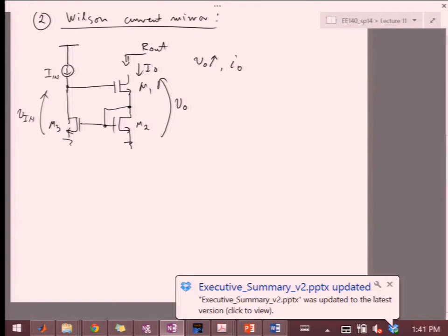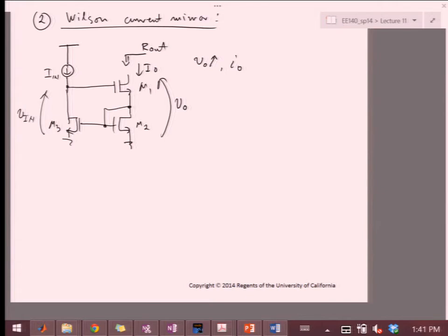It increases because the source has some finite output impedance, right? So if the voltage increases on any given R, your current also increases, right? So knowing that this has some finite output impedance, if I increase the output voltage, likely if there's no other regulation mechanism, this I is also going to increase, right? So if I increases, that means that this VGS also increases because this is diode connected, right? So it maps that increase in I naught to this guy over here.